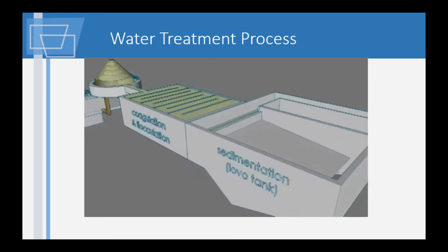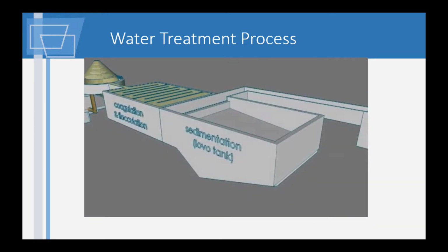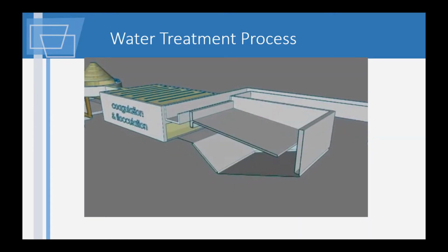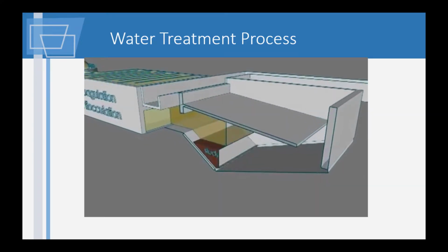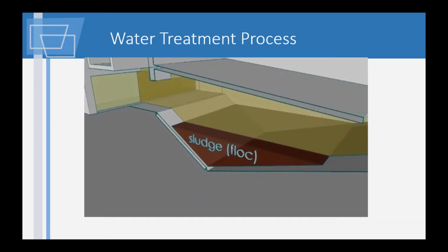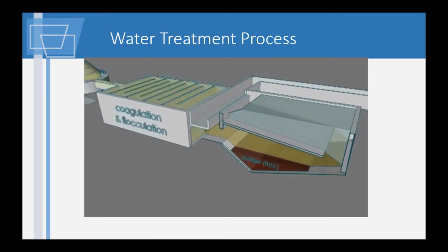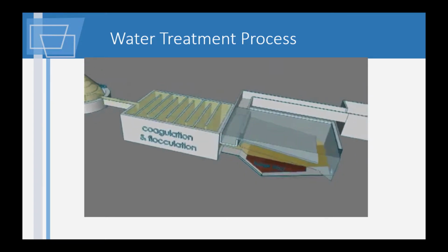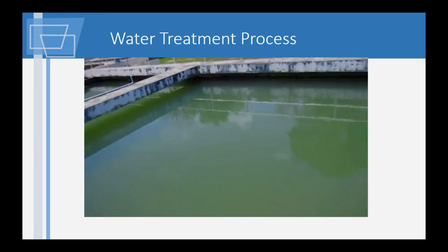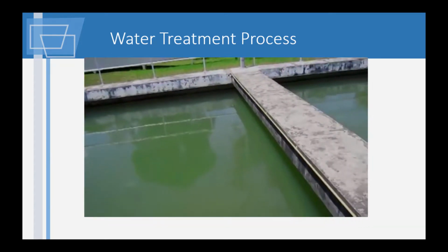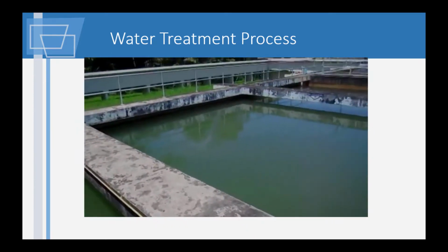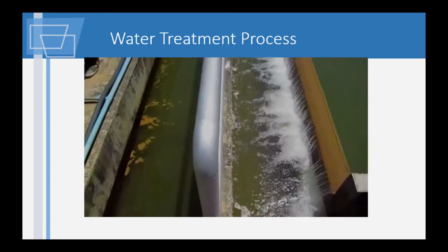The larger particles, or floc, are heavy and quickly settle to the bottom of the water supply. This settling process is called sedimentation. The flocs are allowed to flow through the sedimentation tank as uniformly as possible for long enough period for them to settle. The clarified water will be collected from the top.